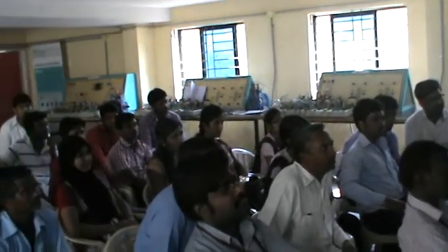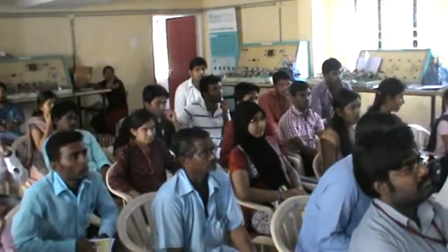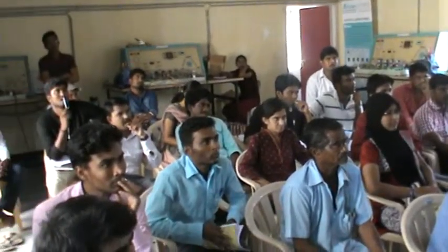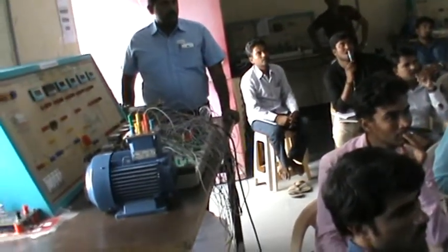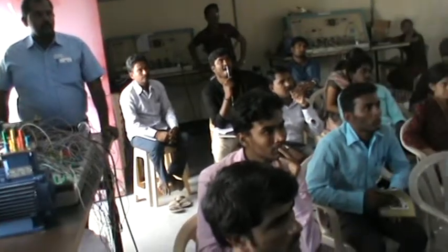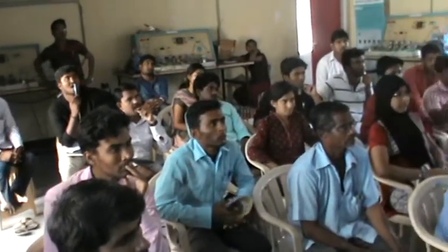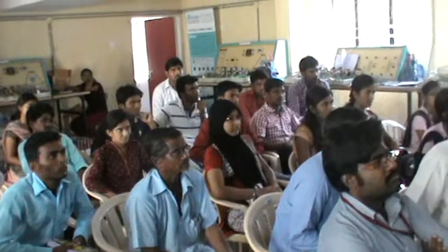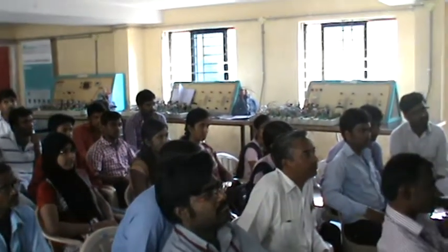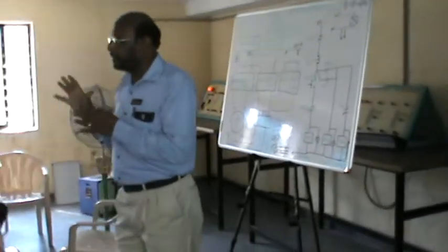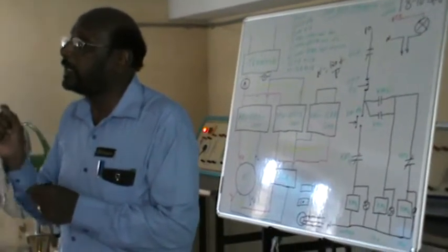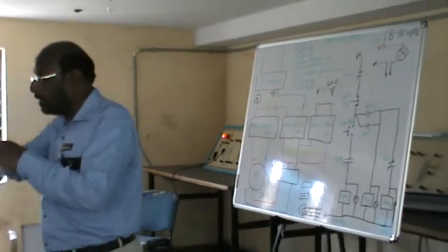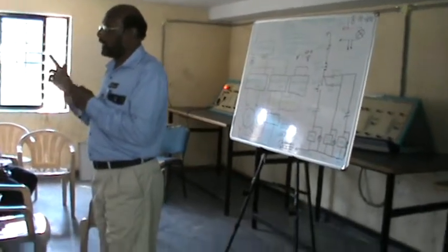Only thing is, first it moves. All the electrons go through a forward action, then a reverse action, and move ahead like that in AC. Whereas in DC there is only one direction of flow. That is why it is called direct current. So in AC, every time it changes the direction of flow. That is called frequency. Ours is 50 cycles per second. That means 50 cycles: in a second, it changes the direction 50 times. That is frequency.